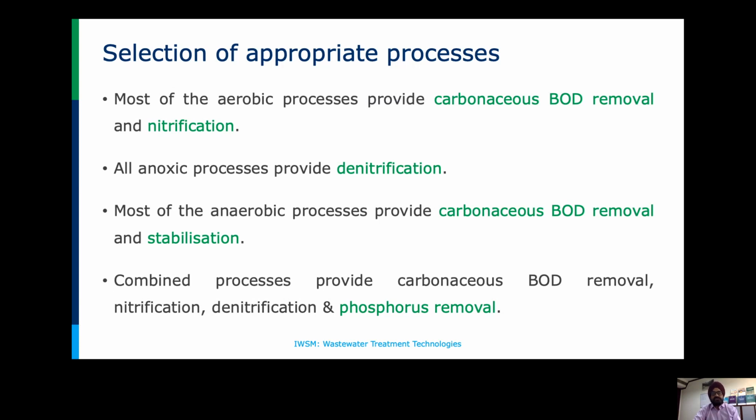It essentially does denitrification. Most of the anaerobic processes do carbonaceous BOD removal, as was said, also nitrification, and they also stabilize, because you ensure that the wastewater comes and is stabilized for removal of these contaminants.